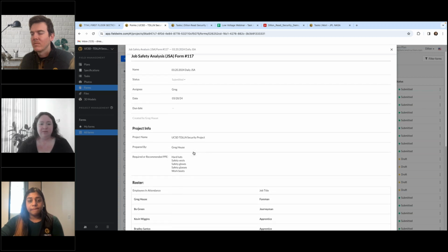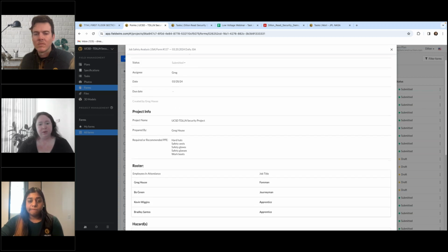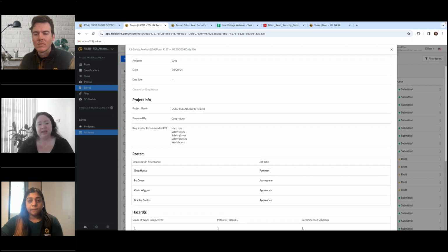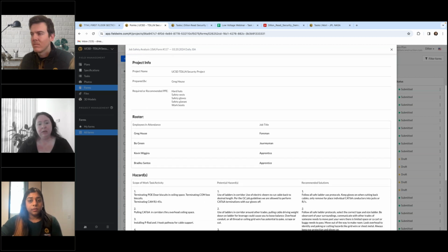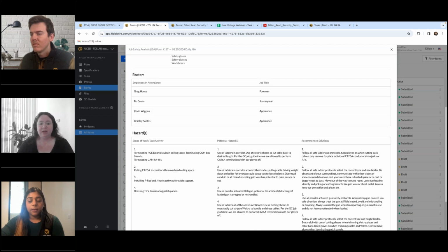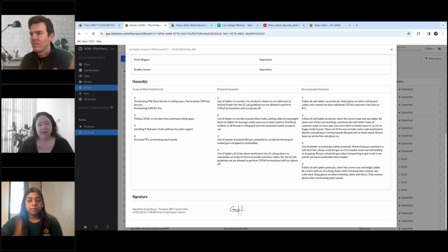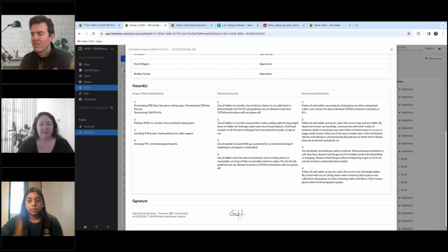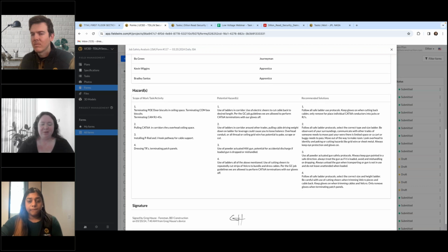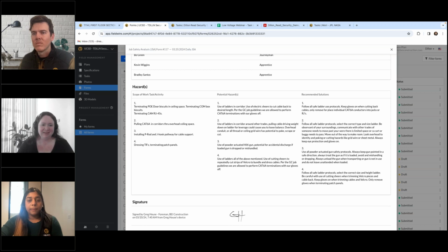So with these, the foreman goes in and records: what are the hazards on site? What is the required PPE? Who's in attendance at these daily safety briefings that we do at the very beginning of every single day? And then we make sure that everything is in safety compliance. You never want a job site held up because you're not in safety compliance.